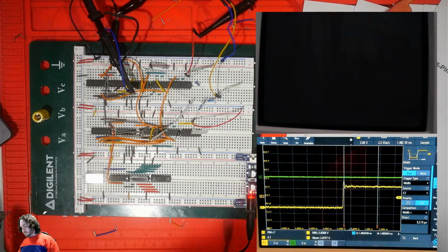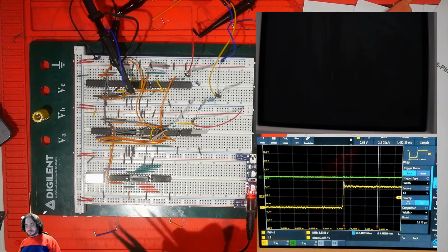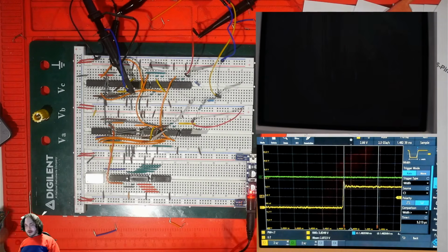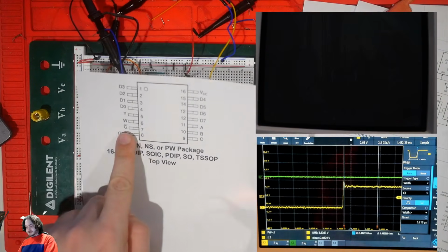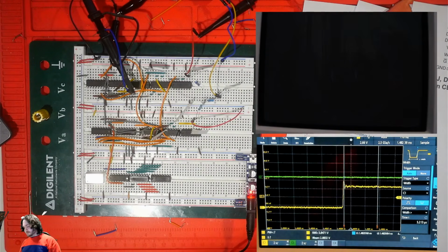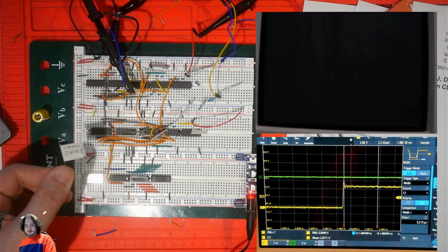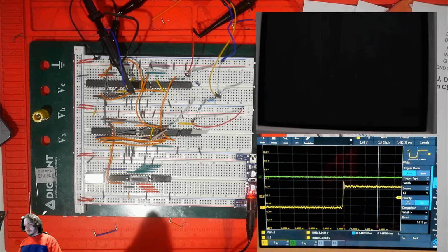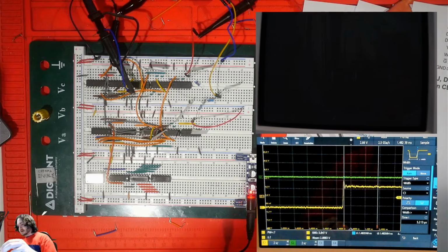Now, this is going to be able to select one of these phases that we've generated with the shift register, but we don't want it to output them all the time. We're going to use that G bar input with another signal that we're going to create called chroma enable. Got a flag ready for that. Chroma enable, let's check my note.